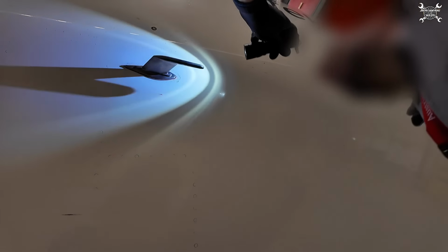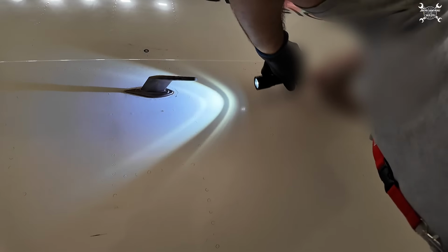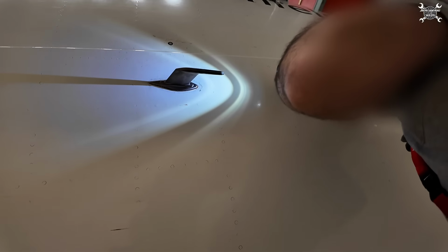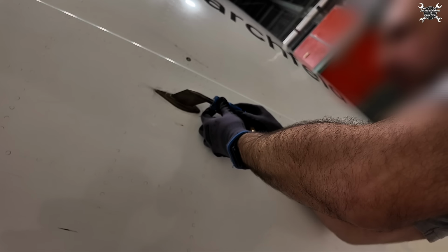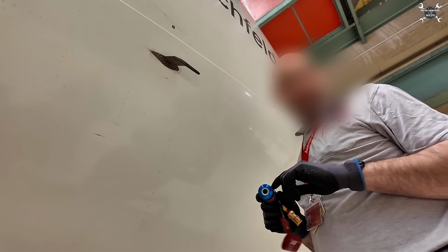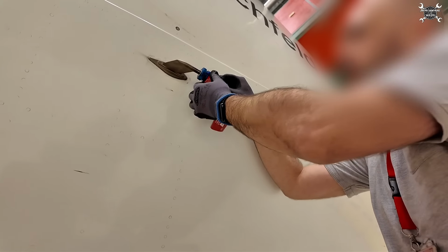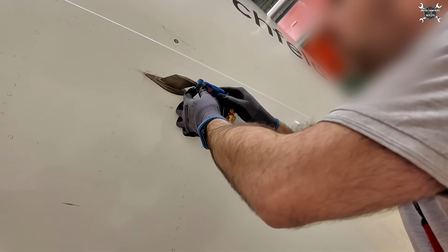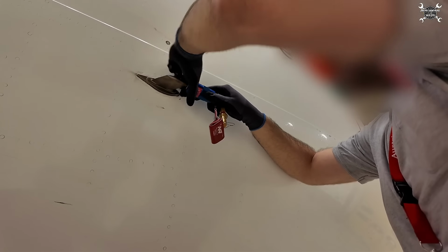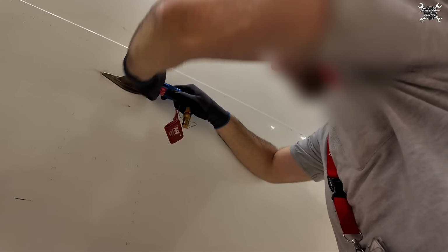Next, we need to install testing equipment also on both pitot probes, but before that we need to inspect if there is no contamination inside of the pitot probe. So we need to go all the way to the static hole. It should be gentle. There's a second seal. If you try to force it, you can damage the inside seal. At some point it stops, and then you have to adjust it a little bit. And then it goes inside.